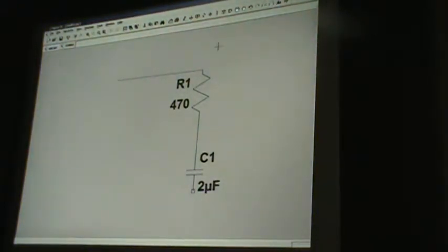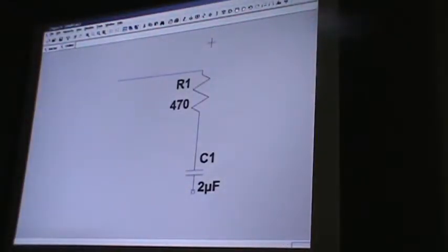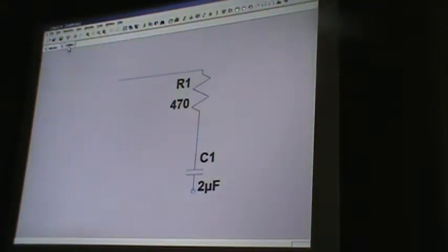You can also do schematic capture in Eagle and then import it into LTspice. Right, that's what I was going to say. You can do schematic capture in any SPICE program and import it to this, and it writes this SPICE format. And you can see where it says wire, and that's the start and end positions of every horizontal or vertical wire that it has in there. Did you write that, or did it create that file for you? It created that file from the schematic, not this one, a different one.